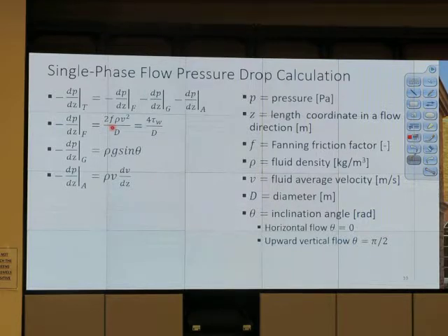Okay. So near the inlet, pressure drop per unit length is not the same compared to pressure drop per unit length away from the inlet. Because near the inlet, some energy has to be used to change the shape of the velocity profile. Later on, we don't have to change the shape of the velocity profile, right? It just looks like that, parabola shape. But near the inlet, we have to do something to change the shape of the velocity profile. So intuitively, that causes pressure drop per unit length near the inlet to be more than pressure drop per unit length away from the inlet. And there's a need for the correction factor.